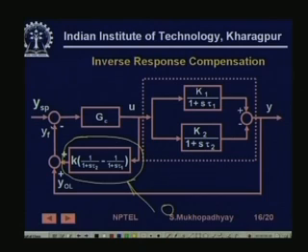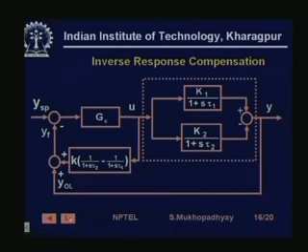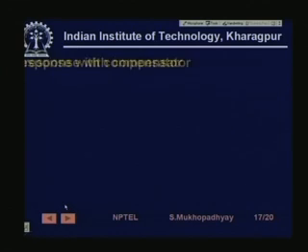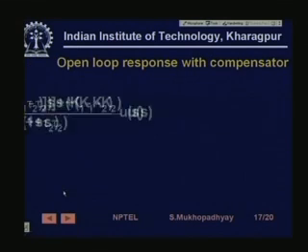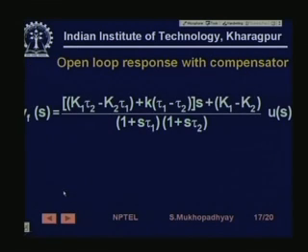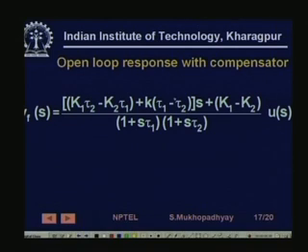Now the plant is seeing this feedback rather than the open loop response feedback. I am now modifying the view of the plant. So now the feedback term, if you calculate, you will get k1 tau 2 minus k2 tau 1 plus k into tau 1 minus tau 2. So this term has been added now. Previously it was only this and it was negative.